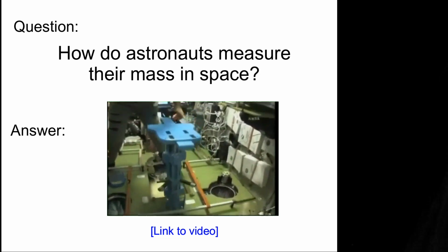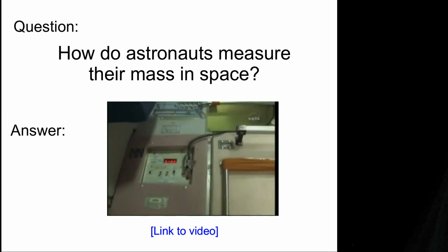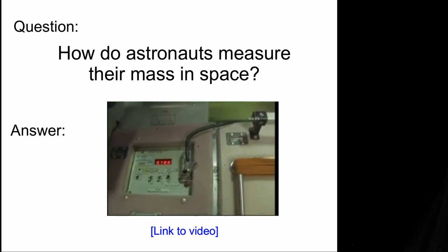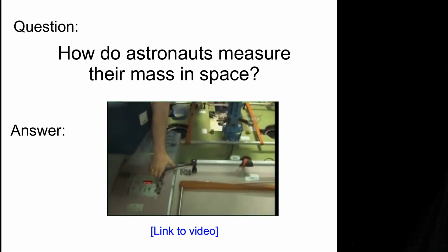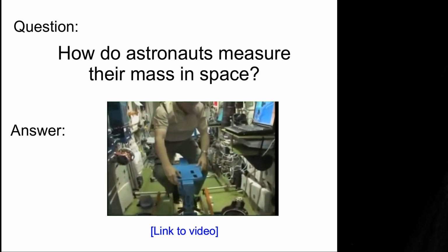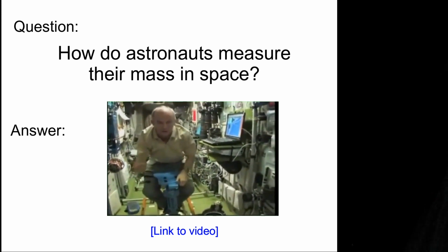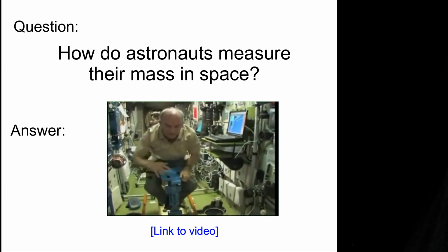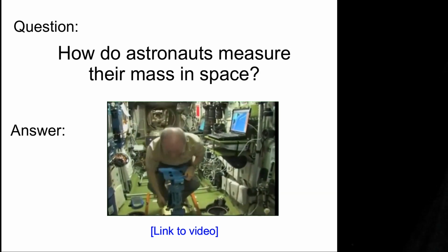And we have an electronics unit over here that gives a readout of the weight, and right now, like I said, it's calibrating. So I'm going to reset it, and we're going to change it to working mode to measure the body mass. I'm going to get on it, and now since we've got my mass on it, the frequency is going to be much less than it was during the calibration. And it will take that frequency, the known spring constant and the known damping ratio, and calculate my mass. So here we go.